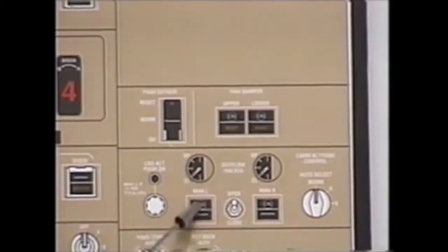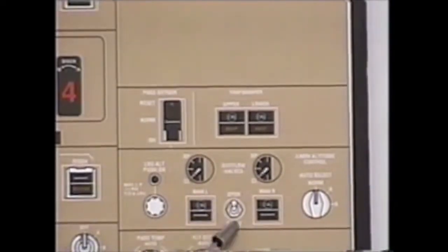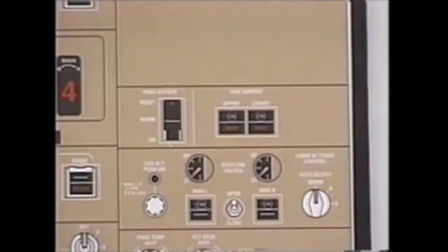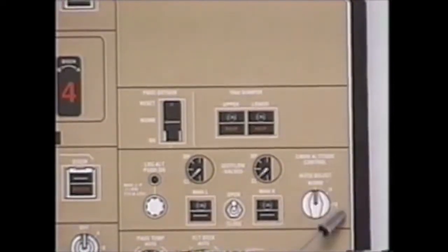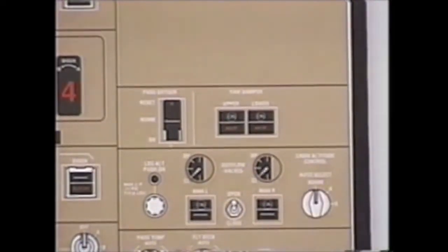If at any time a manual selection is used, using the switch to the open or closed position as desired drives the selected valves open or closed. Whenever the option is selected to manual, the cabin limiter of 11,000 feet is bypassed. Auto selector for cabin altitude control in normal, again, allows the system to alternate between controllers on each subsequent flight, or allows you to select the appropriate A or B controller. Regardless of the switch position used, if the selected controller fails, the other controller will automatically step in.